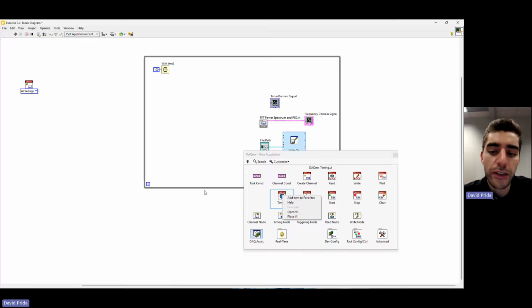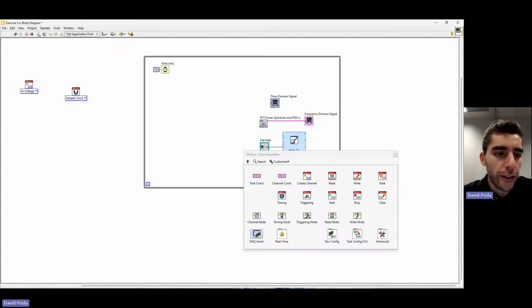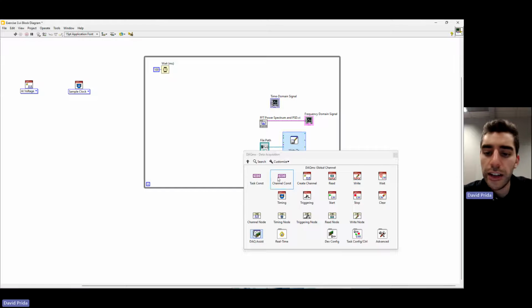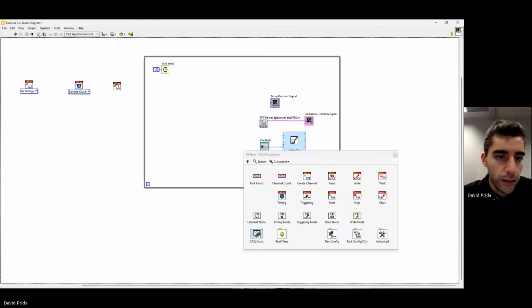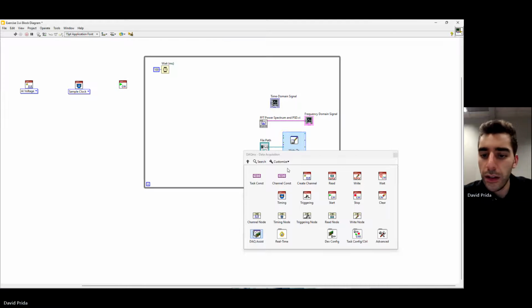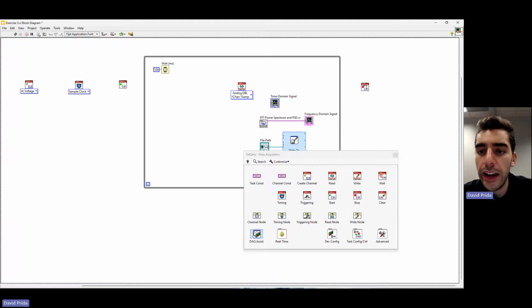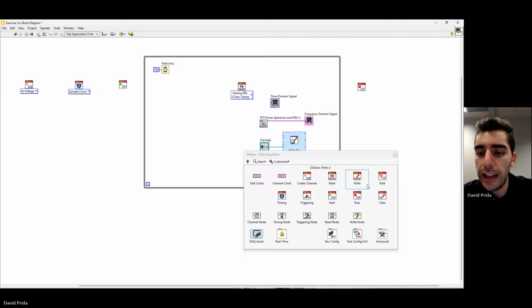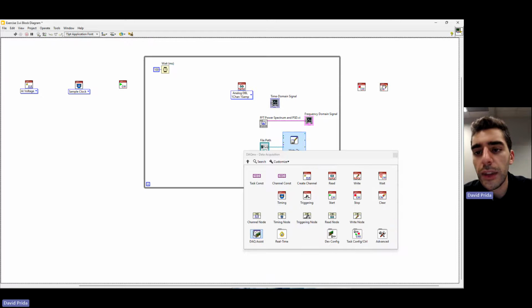So we've added in the create channel. Let's go ahead and add in a timing function. Having trouble clicking it. Click one more time, click to place the item. Then, so we added in our create channel, our timing, our start. Let's go add in a read because we're going to be reading data. If we were generating a voltage signal, we'd go ahead and write that data out. And then now let's go ahead and stop the task and then clear it.